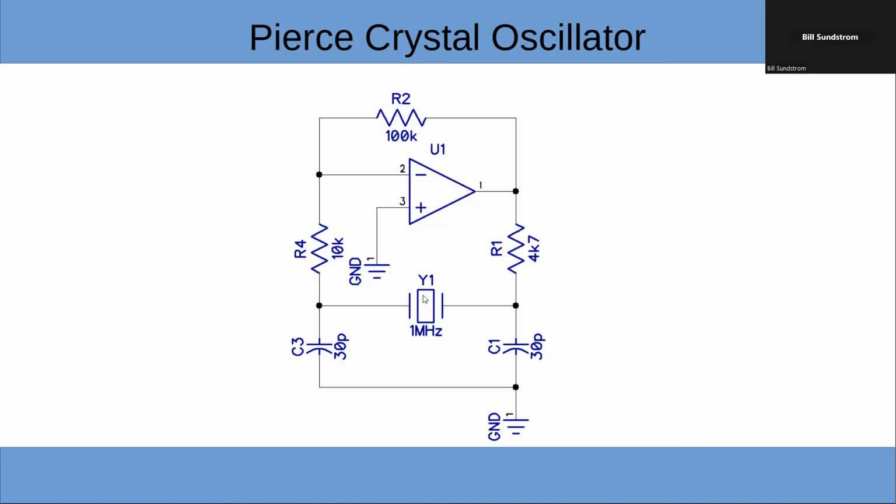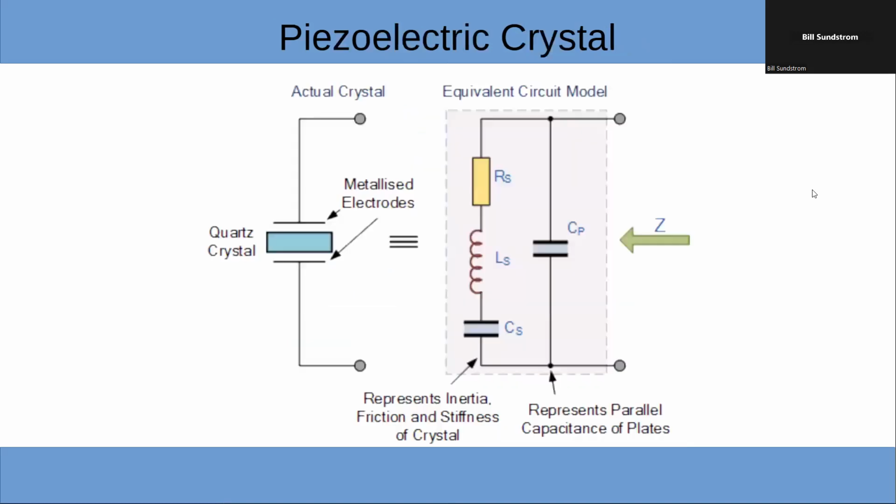And normally on a piezoelectric crystal, it may require some capacitance on either side. It will depend on the crystal, but normally you'll see a circuit like this and you'll have some small picofarad values. And as we talked about piezoelectric crystals, this is the equivalent circuit.